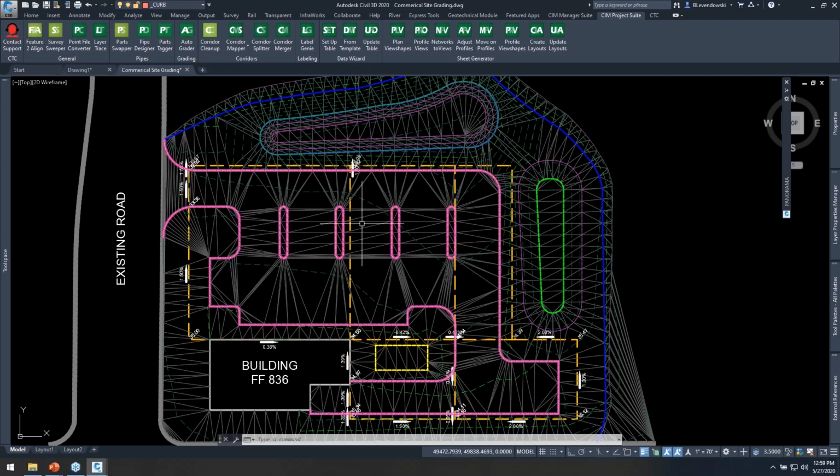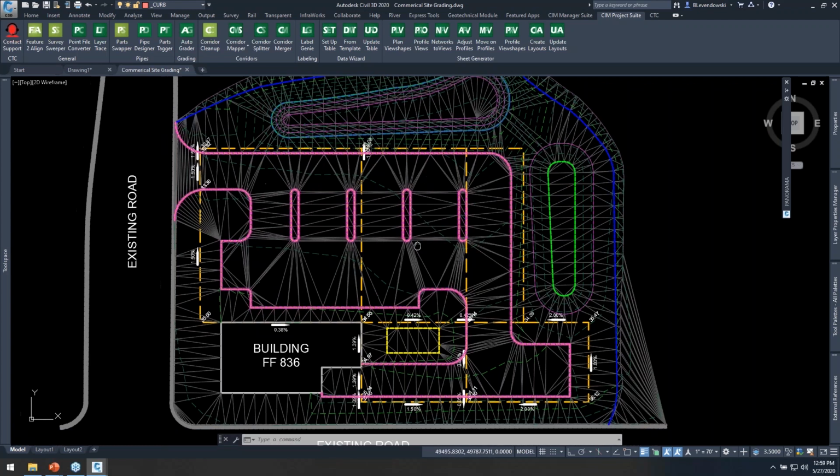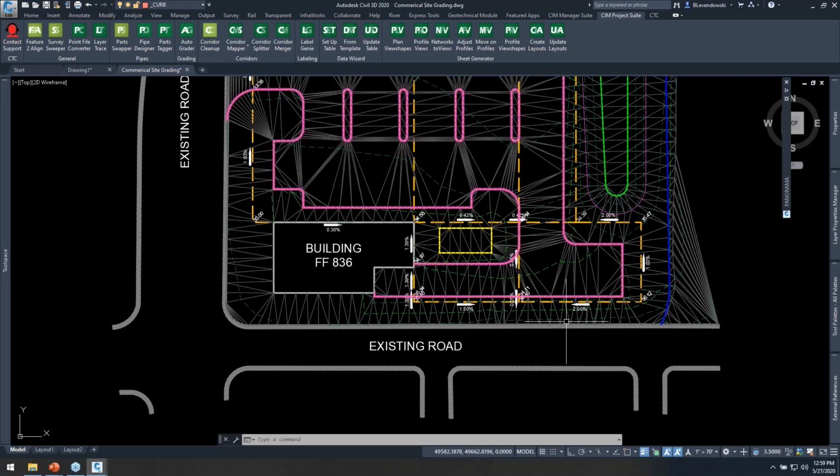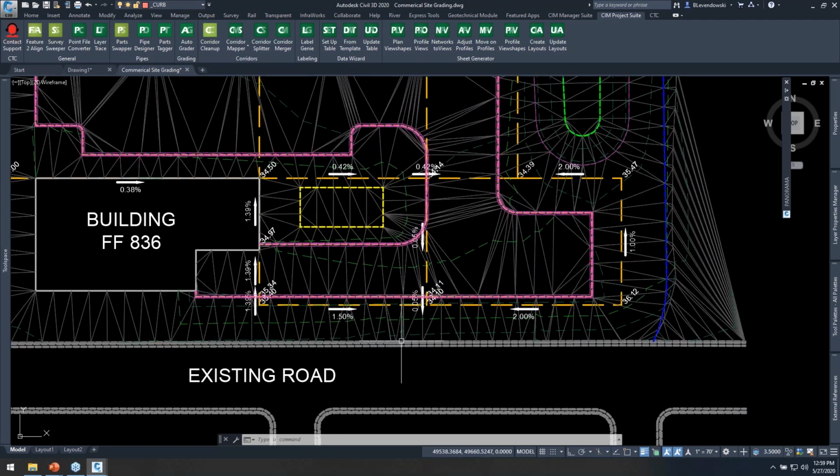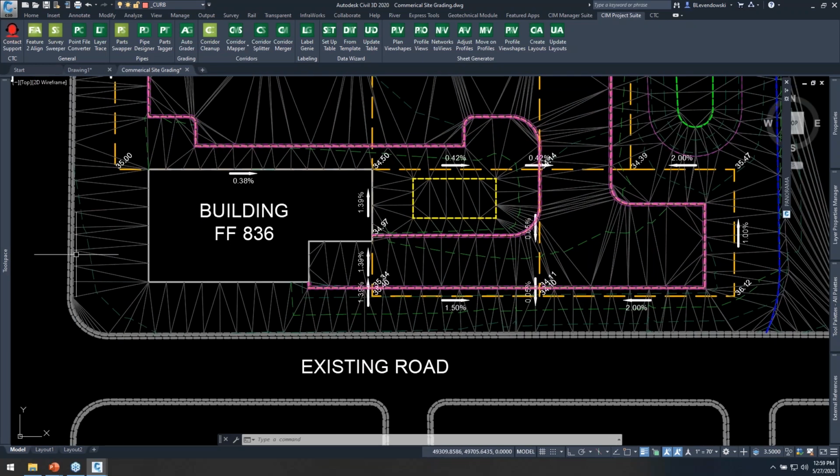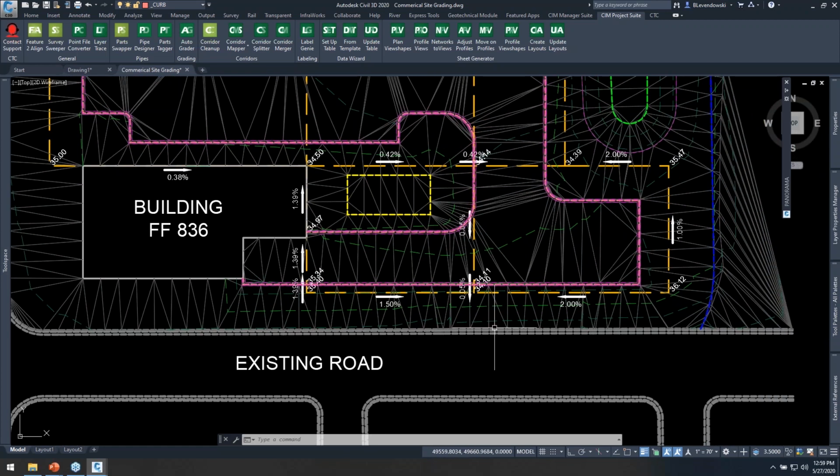So another question came in, if you have a property line at the boundary limit, in fact, this is kind of what I showed here, how do we daylight to that, right? Well, if you have a property line there and there's existing grades you have to tie into, and you already have that geometry defined, it's just a matter of creating a feature line like we had, pulling those elevations from existing grade and throwing it in the same surface.